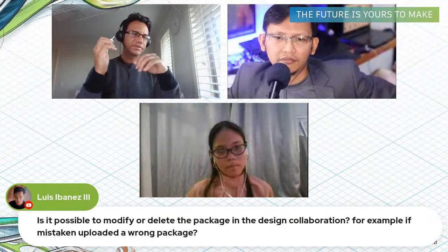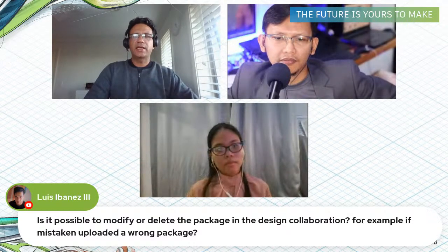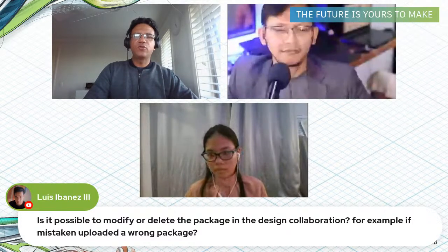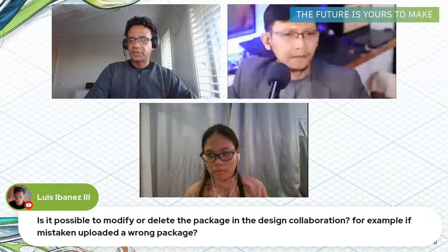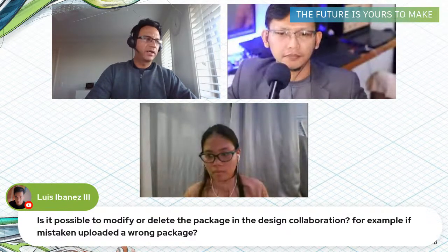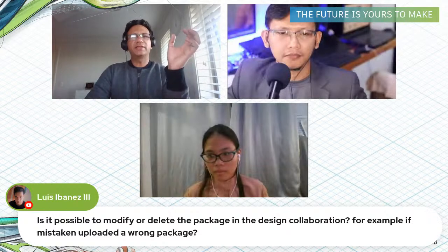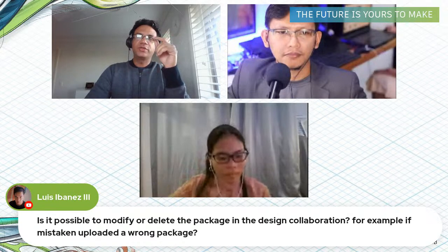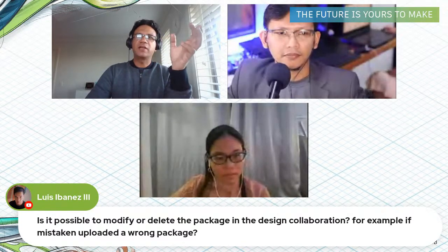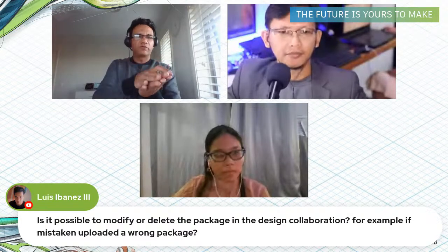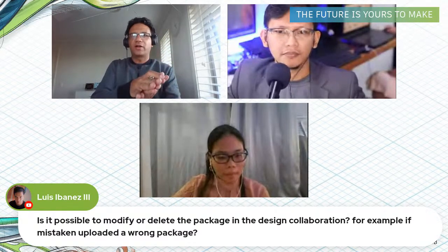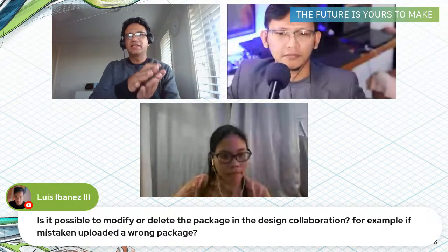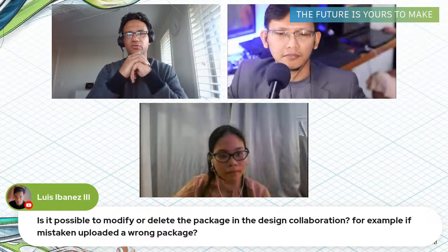Okay, so what happens is you can delete a package from your swim lane if you have not shared the package yet. As soon as you have shared the package, then you can't delete it. But what you can do is, for example, let's say you made a mistake and you shared the wrong package. Then you could create and share the right package. And what it does is it then overwrites the old files with the new set of files, which means that the other disciplines will not see those older changes. They'll see the new model with the new changes.